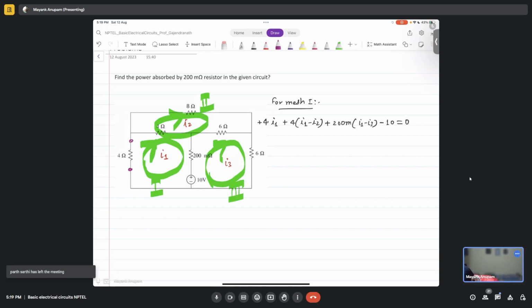While going from here to here in this direction, if the current is flowing, we have a voltage drop across the 4 ohm, so I have taken plus 4 into I1. The voltage drops are considered positive and voltage increments are considered negative in writing this equation. Going in this direction, (I1 minus I2) is flowing across this 4 ohm resistor, and the voltage dropping across it will be 4 into (I1 minus I2). Similarly here also the voltage will be dropping, it will be 200 milli into (I1 minus I3), right? But across this 10 volts...